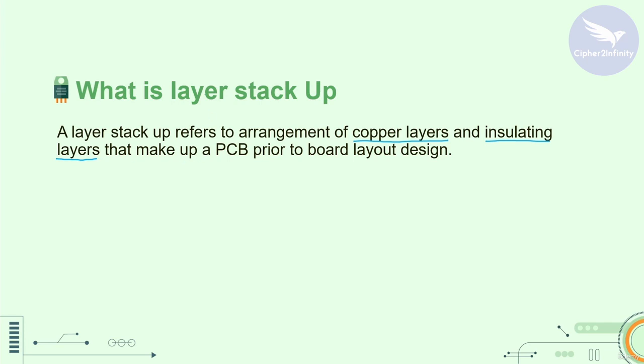We need to think about this layer stackup before we start with the layout design of our hardware. So always remember, whenever you start with the layout design, first of all you have to think about the layer stackup. Now in our case, as we are dealing with a 2-layer PCB, the layer stackup is actually not that complicated.